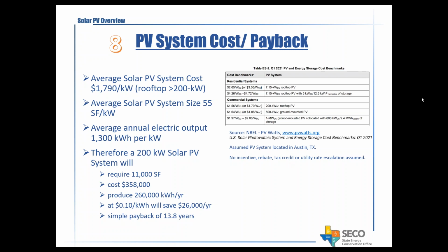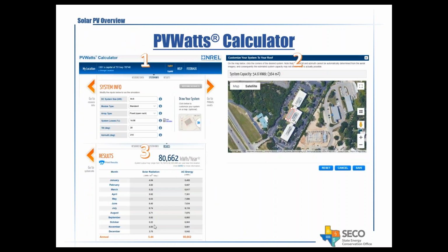Looks like we have a question from one of our viewers. The question from one of our attendees was, does the PVWatts website or calculator account for shading from buildings or trees? And the answer is yes. Let me see if I can show y'all real quick. On this slide, under the system losses, we can go into this, and there's a drop down where you can go into an even higher level of detail, and there's a loss calculator that will break it down into the different types of shading or different effects.